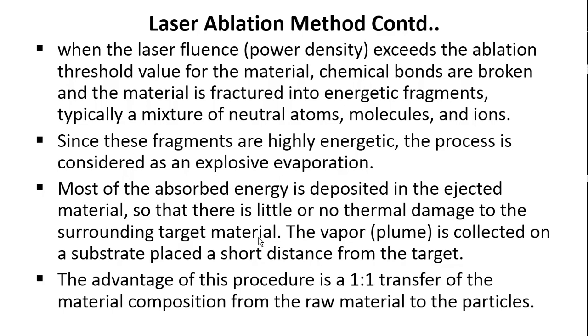But here you should see that the energy absorbed is completely deposited upon the ejected material, completely transferred and available on the ejected material, so that this ejected material will usually be condensed as nanoparticles over the substrate. That is why there is no thermal damage occurring at the target material due to the application of laser.